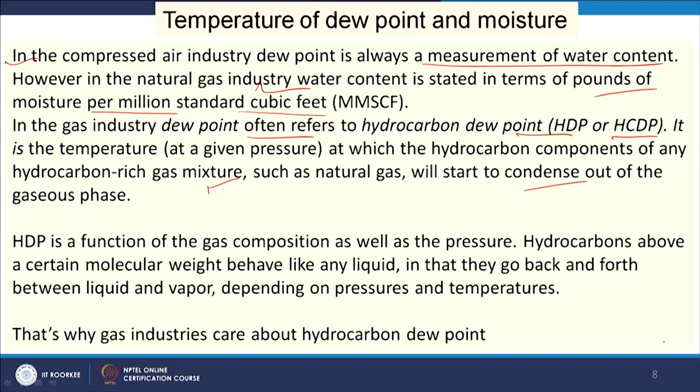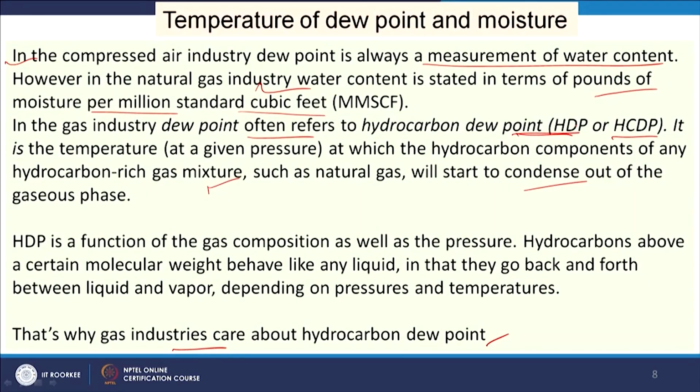We have seen that higher molecular weight hydrocarbons give higher heating value, that is, LPG has higher heating value, and in this case liquid and gas phase transfer is also possible depending upon the pressure and temperature. So, industries care about the hydrocarbon dew point. Dew point will influence how many molecules will be in the gas phase. Gas phase means it is easy to use, and the liquid phase with higher hydrocarbons gives us more heating value. So, the hydrocarbon dew point is important because it decides whether the hydrocarbon will be in gas phase or liquid phase. That is why the hydrocarbon dew point is considered by the gas industry.